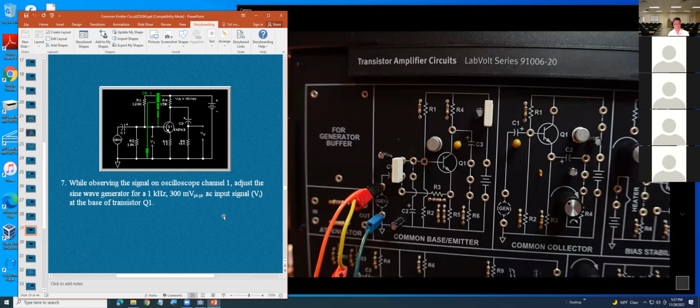Now, I don't do anything on the DC, okay? That's a very simple thing. You can use the DMM to measure the DC voltage here, here, and here. You can get VB, VE, and VC. So any DC measurement, do you have any questions? Aren't you supposed to measure your DC input?